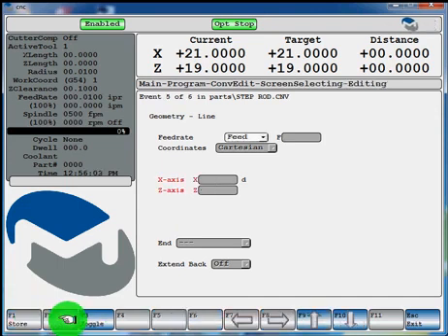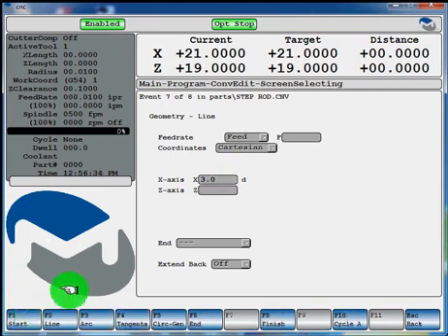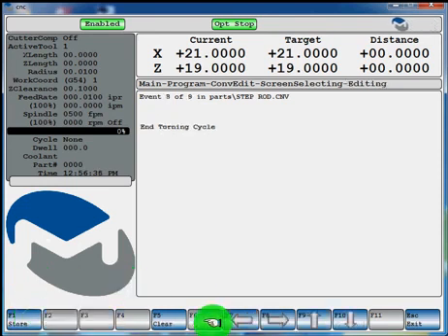Now another line. And our diameter now at this area will be 2-inch diameter. F1 Store. Now another line. Now with the 2-inch diameter, we'll turn it back to 1.5 inches in Z. Hit F1 Store, F2 for another line, and we'll turn it out to a 3-inch diameter. F1 store, F6 end your cycle, and F1 store the end of cycle event.